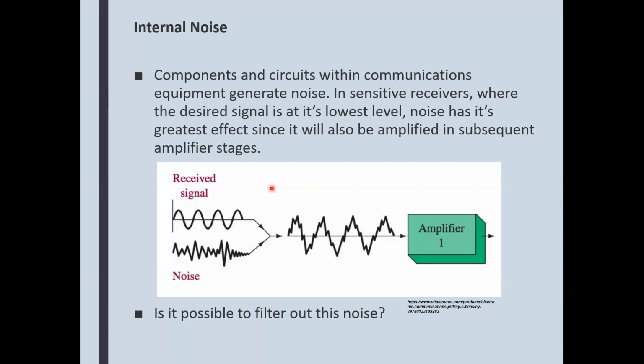So the filters would be applied either at the entry point to the house, so the internet noise would be filtered out and sent straight to the modem, and the rest of the signal would go to the rest of the house. Or you could apply individual filters on every phone. So yes, sometimes it is possible to filter noise, depending on the type of signal.